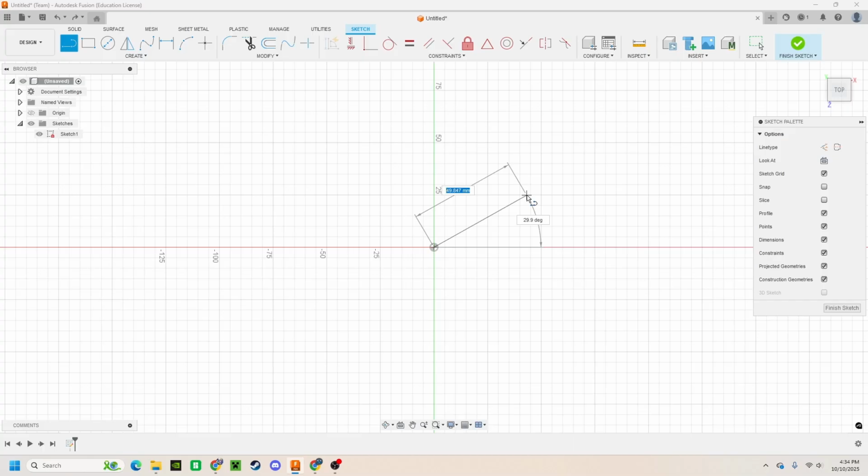This allows us to select each label and set the distances that we want. Start by changing the length to 50 millimeters and the angle to 45 degrees and press Enter. This allowed us to constrain the line and give it a fixed position. Go ahead and delete everything again. Create another line, but without doing that dimension step, and press Escape.